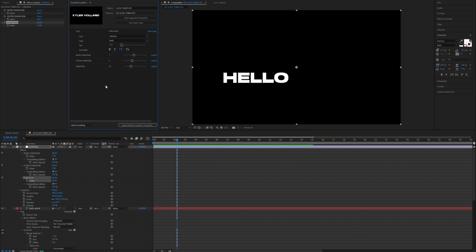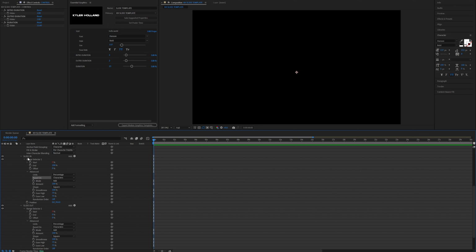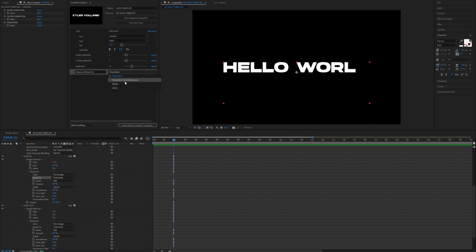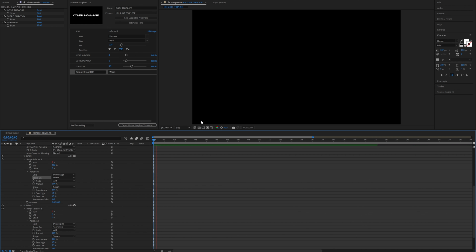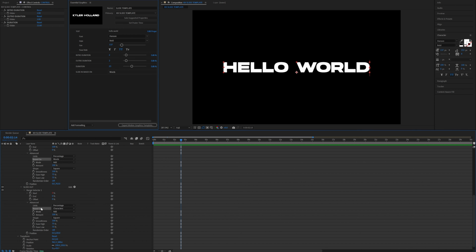Next, let's start looking at what else we can include in here. For starters, we're going to be working in the slide in only right now. And I want to drag in the based on. So the based on will allow us to change what the animation is based on. For example, I have characters selected. I can choose words as well. So it will slide in each word. Let's name this to slide in based on, just to stay organized. And equally so, we can actually drag in the slide out based on.